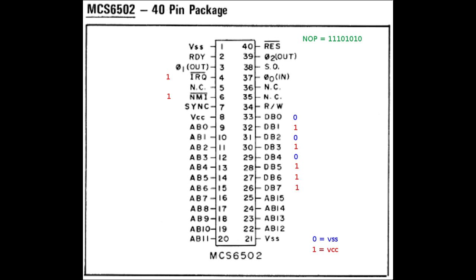And what happens if we are running a NOP generator and we get an IRQ or NMI is that the CPU will stop executing the NOP sequence and make some writes on the stack area because it wants to save the current content of the program counter, and also write on the stack the content of the status register of the processor, and finally jump to a location that is contained in a couple of locations in the FFFF address space, and will start executing the NOP over and over again.